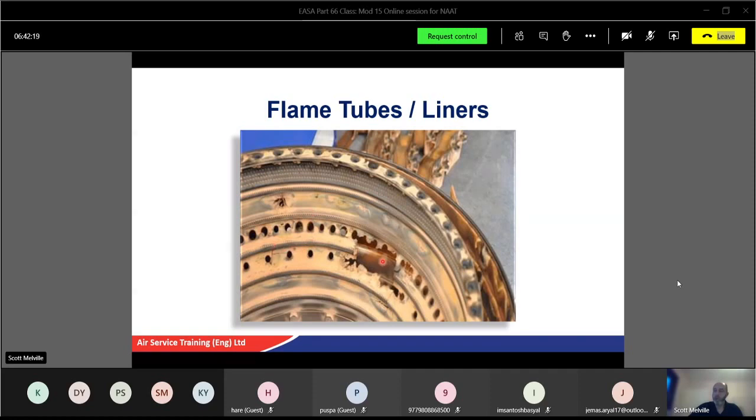Again, this one's obviously gone to a bit extreme. It was probably still working, but you probably had hot air coming out of there. You probably got an LP cooling overheat detection as well. Again, more hot spots. So again, potentially the burner is not doing its job right.